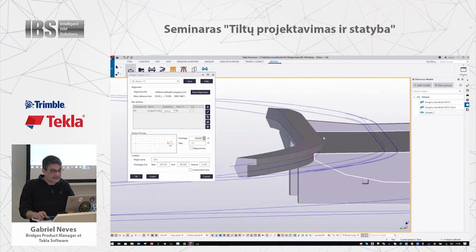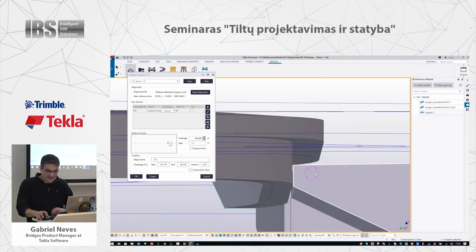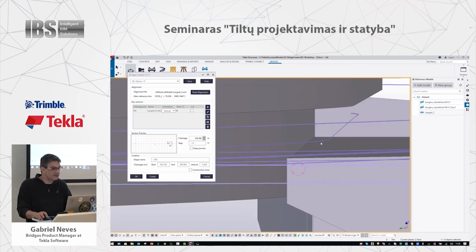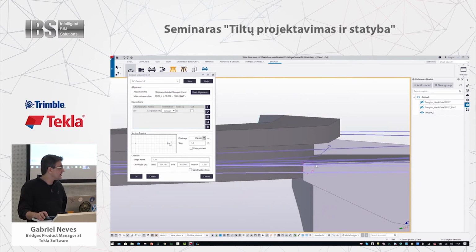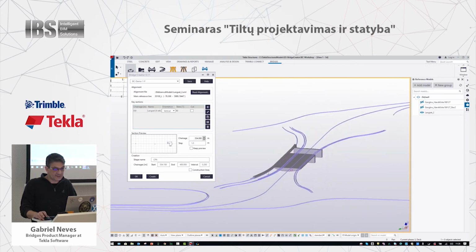And this has a spacing, now too much because I played so much with this model. This has a spacing constraint, 25 mil there, and here now is too much. I need to put this down, but could be precast, but could be a second pour. So we just put 0 constraint there, top and side, and then we'll have the edge beam as in situ second pour. So this is one example.